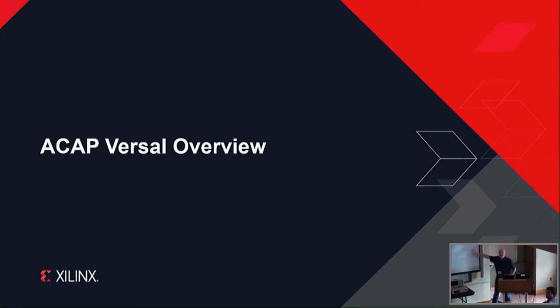It uses all standard Xilinx parts. Okay. So currently, let me say, first of all, let me answer for the original PYNQ on Zynq devices. So that's the ARM processors and the FPGA. We reconfigure the FPGA in its entirety. Okay, so every time we bring in a new notebook or load another overlay, it comes down in its entirety. That's the majority of our examples.